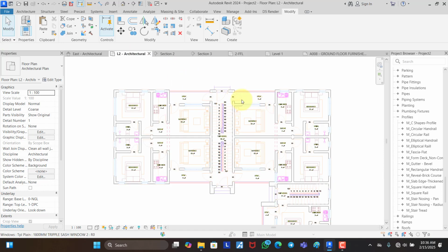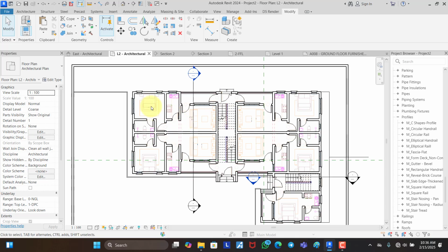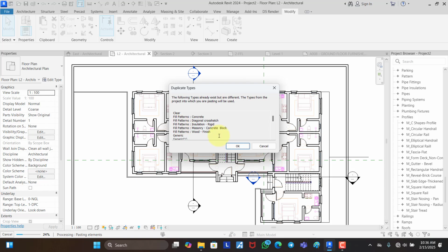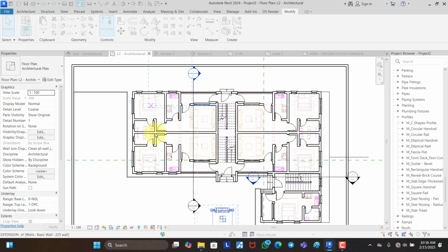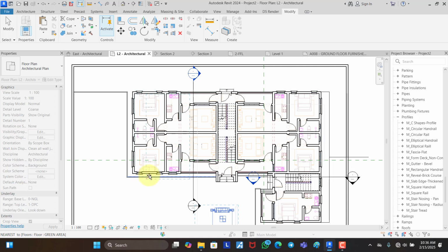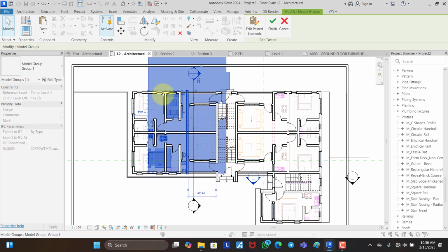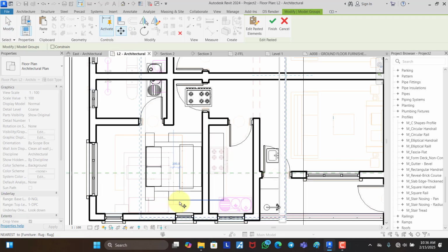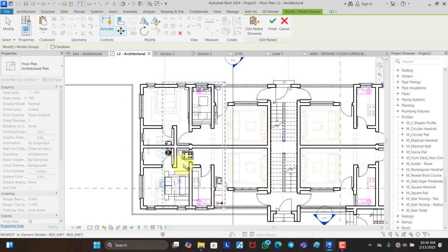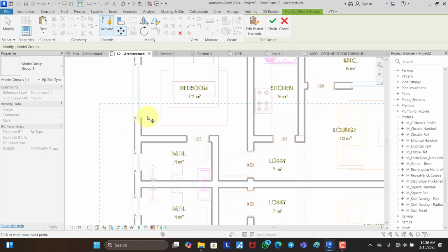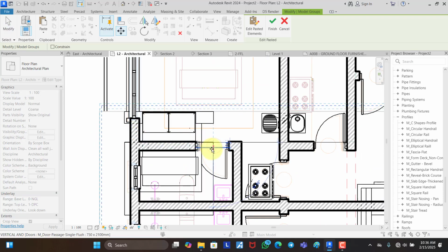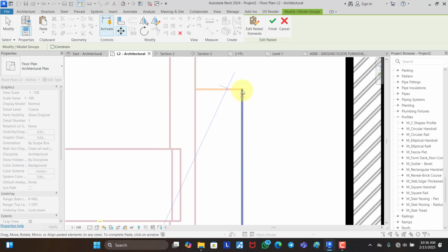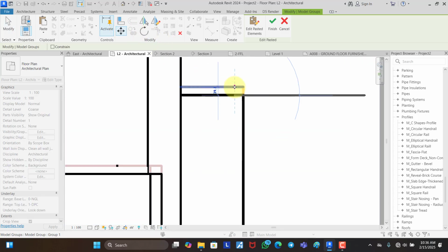Okay, so I have copied the components I want to import. Now I'm just going to Ctrl V to paste them here. Okay, so I'm just going to paste it at this point, and let's see. Okay, then we move. Now you can see, let's rotate this first of all 90 degrees, 90, enter. Okay, then we can move this from here to this point. Okay, perfect.